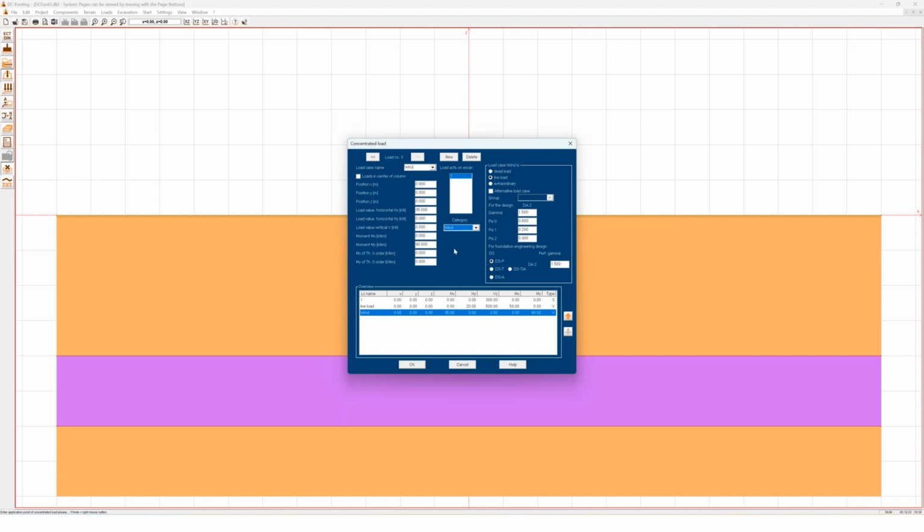And yeah, what we did is that we have chosen a load category. And each load category has its own C values according to the Eurocode. And you can choose the category here. And yeah, the C values are filled out automatically. So you can see here the wind has different C values than the live load over here.